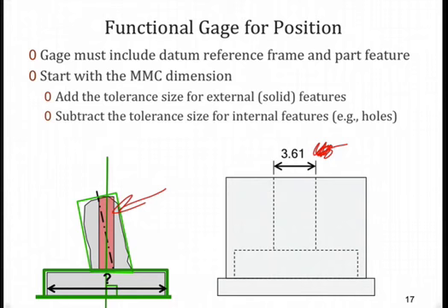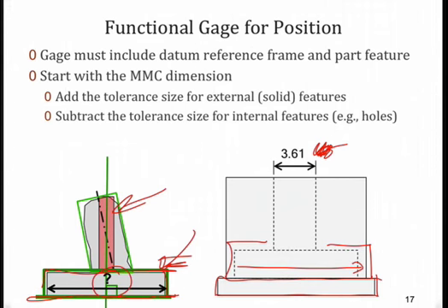We also have the internal feature here meant to establish B, and we have the same feature, which is a separate component, used to establish datum A. On the left here, you see the mating envelopes that are required. We need to determine the surface for A, and then we need a mating envelope to determine B. The question is, what size is that? In other words, what size should we make this internal feature in order to accommodate our parts?